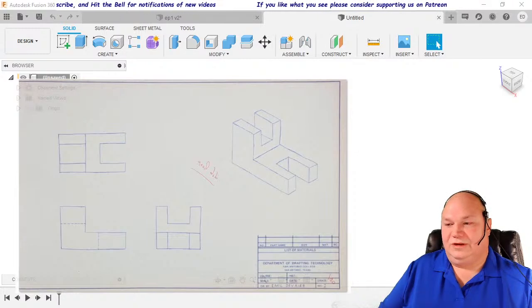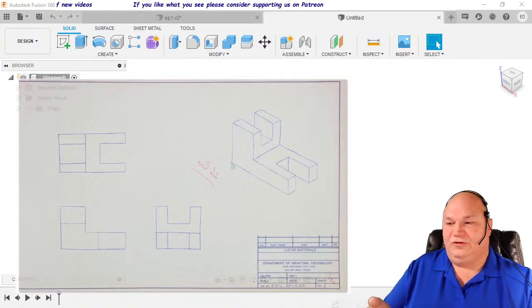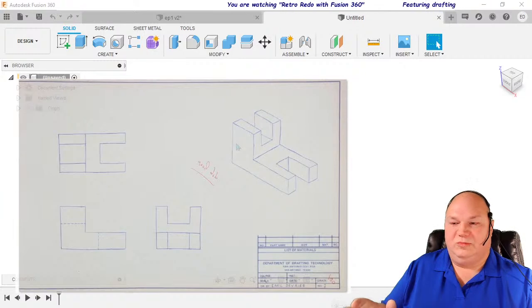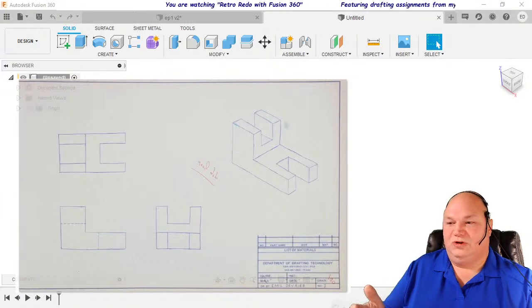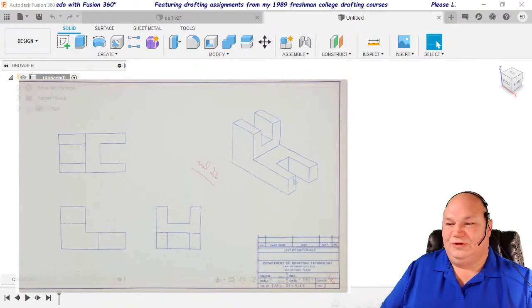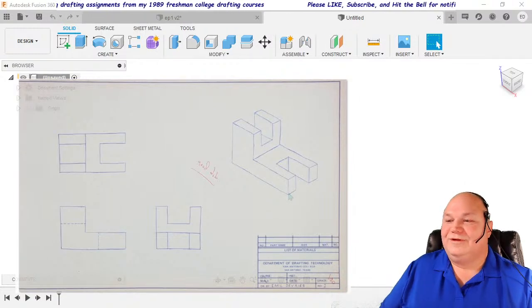Ideally, if you can, like this bottom corner here of the bracket, if you can define all your dimensions from this point, and all of these dimensions from this plane, then that's a reference that never changes throughout the machining. So pretend that, for example, this is one humongous block of metal. We're going to start with one humongous block of metal. We're going to assume this distance is 1 unit, and this distance is 2 units, similar to the ones before. And then we'll kind of go from there. Sound like a plan? Sure.